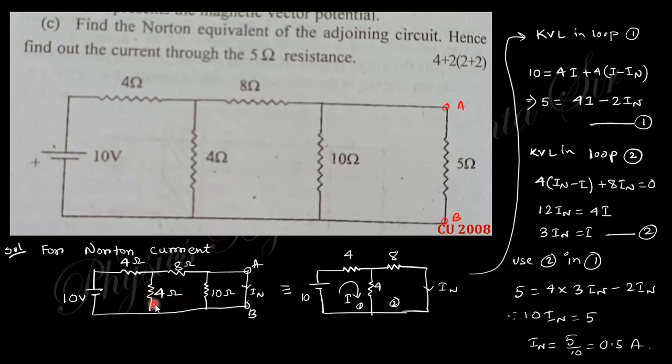So finally, you can see that is 10. And when this is sorted up, you can see these two are parallel. So resistance parallel with short means this is equivalent to 0, because 0 into 10 by 0 plus 10, multiplication by summation, becomes 0. So this will be like 1. So finally we get this one.